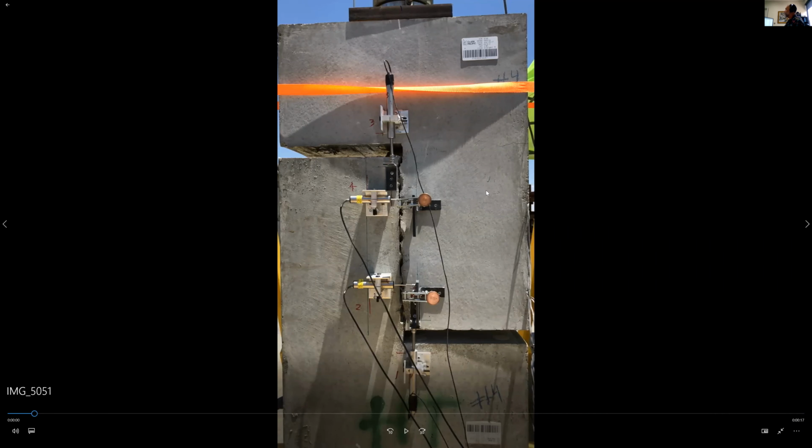This L-shaped piece of concrete was made from a lower grade concrete that was cast up against the lower L shape, which was higher strength concrete that was cast a few weeks before. So this is hardened concrete. This was wet concrete poured up against it. And then we let the two cure for a couple of weeks, and then we tested them, and we started testing them this morning. So what we're testing for is this interface.